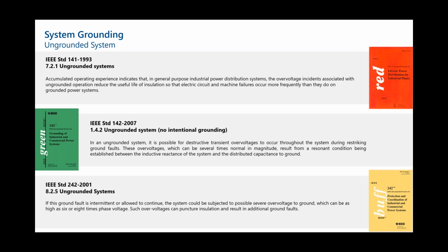So when these transients occur in these ungrounded systems, we can basically have a very hard time in terms of troubleshooting this type of system, since we'd have to isolate every single breaker and figure out where the ground fault is coming from, first of all, and then second of all, if that even solves our issue, how are we going to deal with the damage done from the transients while that ground fault was still in the system?